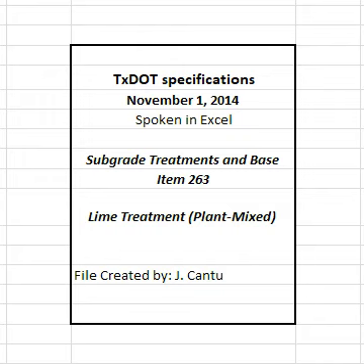Determine the new maximum density of the reworked material in accordance with TxDOT 121E when density control is specified, and compact to at least 95% of this density. The contractor has the option of removing the failing material and replacing it with acceptable lime-treated mix.